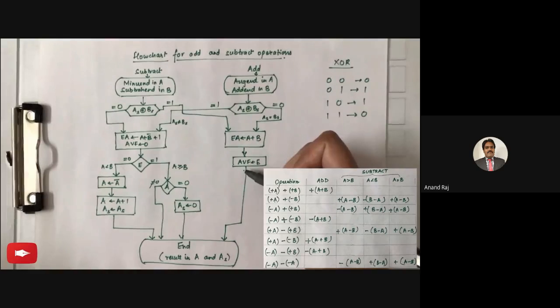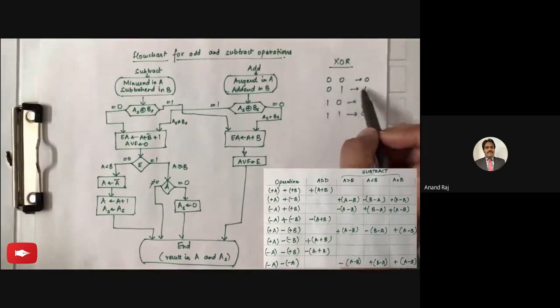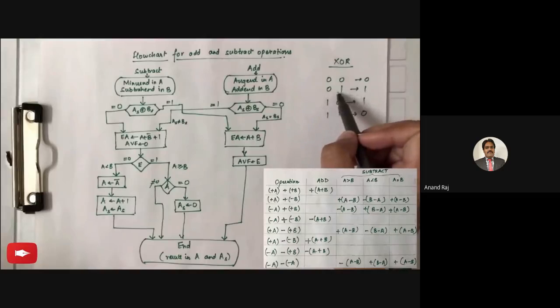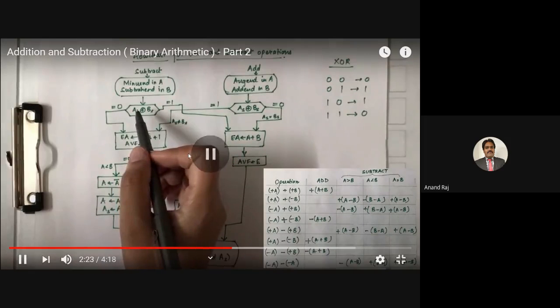In the second and the third case, where the sign of the two numbers was different, subtraction was performed. So what we are doing here is, in these two cases where the sign bit is different, the XOR gate results in 1, and it will go to the subtraction part. Similarly for the subtraction part, if you remember, when the signs...